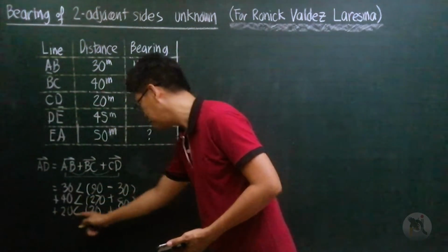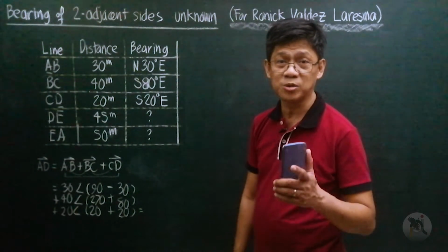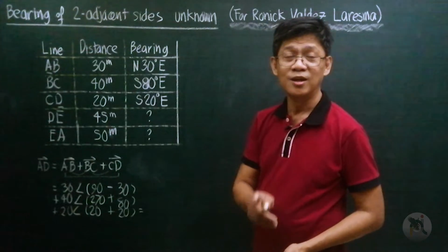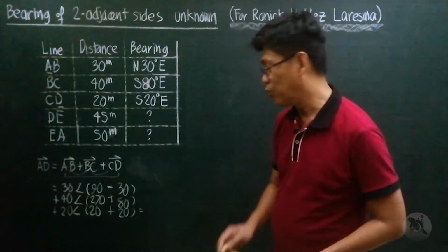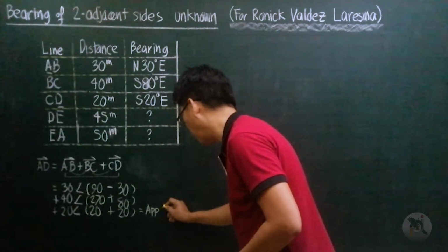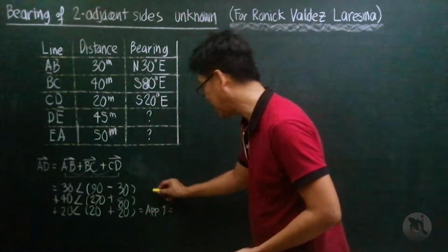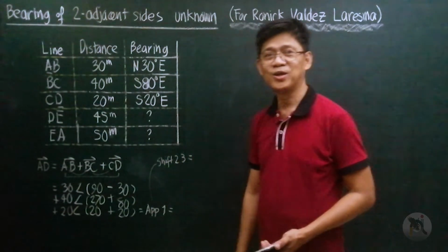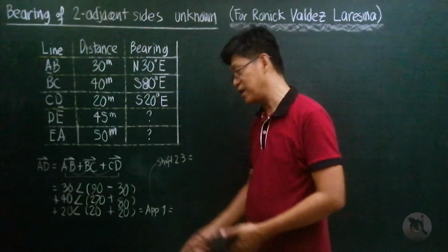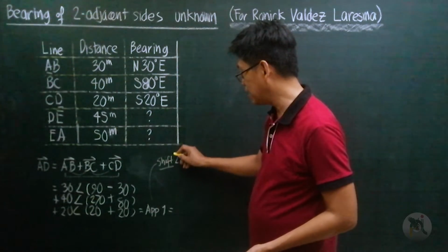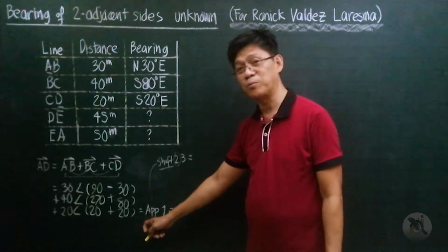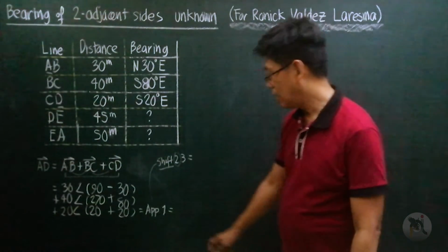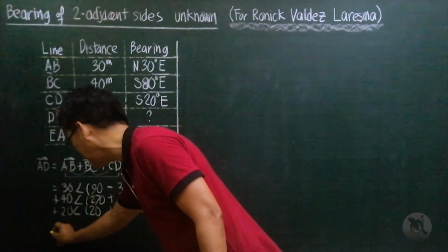So you compute this, then press equals, you'll notice that the answer is in terms of x plus iy. That is x component, y component, departure and latitude. Convert it to R angle theta. In Canon, you just have to press up 1 equals. In Casio, you have to press shift 2, 3 equals. So, different conversion in Casio, you have to use the shift, then the corresponding number. In Canon, you just press up, and everything you need to convert will be there. Okay? So, up 1 equals, then you'll get the answer in R angle theta.